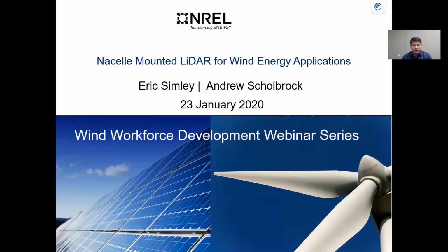I see remote sensing devices, especially LiDAR, as having the potential to make wind turbines and wind farms even smarter. I'm sure economies of scale and technological improvements will bring cost further down. Cost may have already reduced significantly from when we first deployed them, back when the J4 was being tested at the Renewable Energy Research Laboratory at UMass Amherst. One company was then working on a Windicator laser wind sensor for wind energy applications. There are various types of nacelle-mounted LiDARs, such as J4 DM. I'm sure presenters today will elaborate on them.